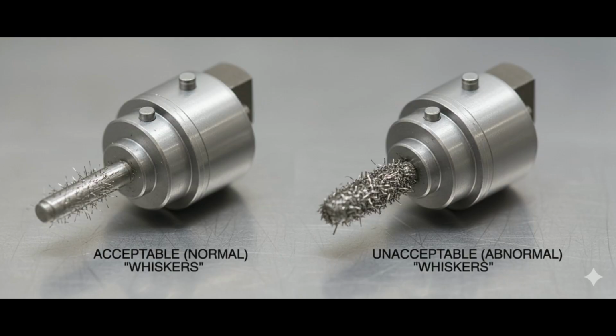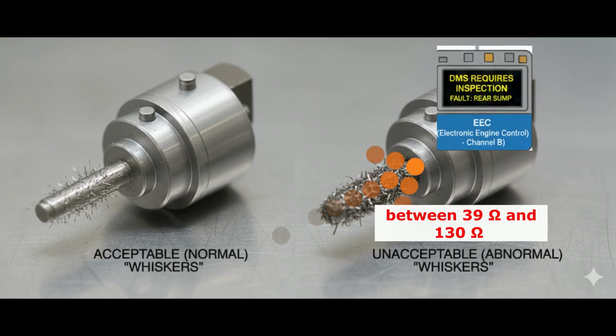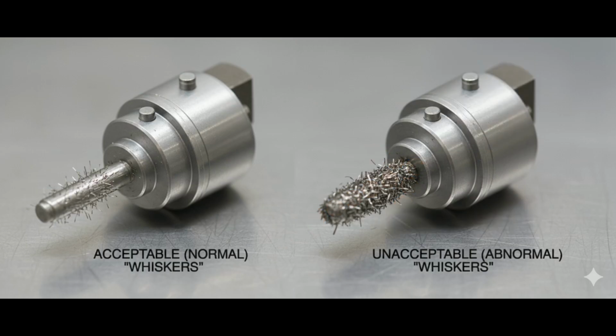Resistance value interpretations. The DMS interprets the resistance values as follows. 39 ohms to 130 ohms maintenance alert. If the resistance value is between 39 and 130 ohms, a maintenance required message is transmitted from the DMS to the control display unit. This indicates that metallic debris is beginning to accumulate, potentially signaling a clogged condition.